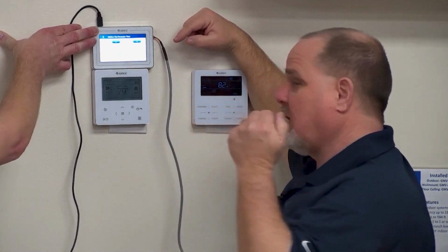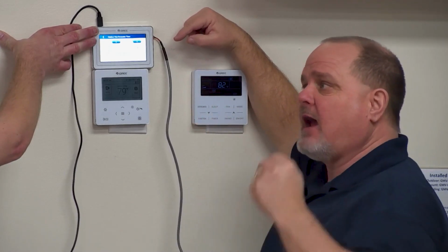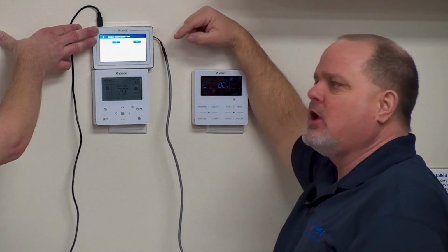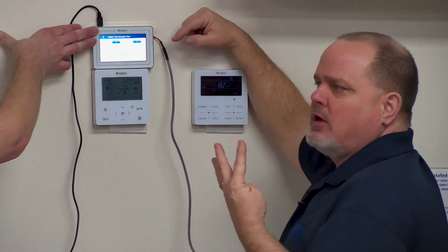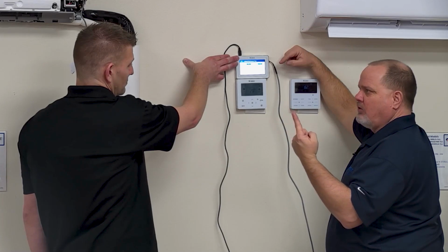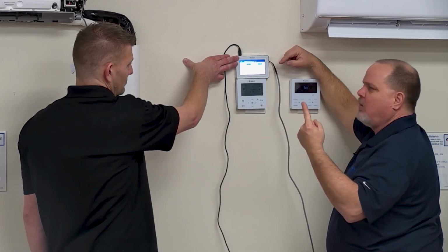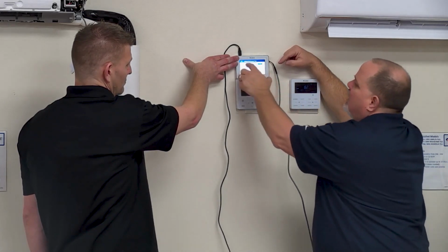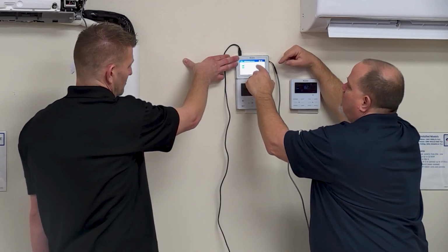Again, that goes back to what I talked about yesterday with the mini split. I may have enough refrigerant in this machine. If I've got 4 indoor units, I may have enough refrigerant to satisfy one, but when I bring in all 4, now I don't have enough refrigerant anymore, and that's why it can't keep up. With all 4, I'm low on gas. So if I start shutting units down and all of a sudden my temperature rise goes up on that one, and my temperature split on my indoor unit...